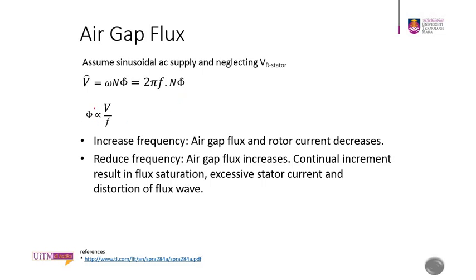With an increase of frequency, your air gap flux and your rotor current decrease. And by reducing the frequency, the air gap flux increases, and with continual increment, you have flux saturation, excessive stator current and distortion of the flux wave.